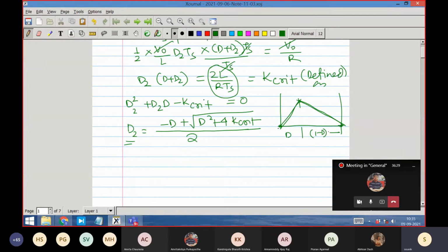That is called the boundary condition, the border between continuous and discontinuous conduction. If the current shifts further, it will be either in continuous or in discontinuous conduction. One may say that this is also a continuous conduction, because precisely 0 to 0 will again give us the volt-second balance. Actually it is a two state, but take it as a bounded thing.